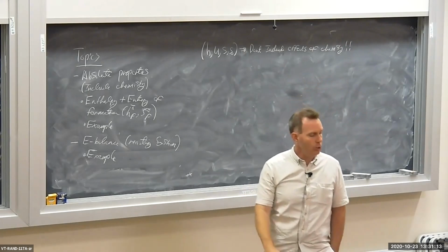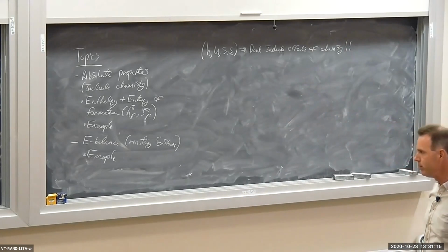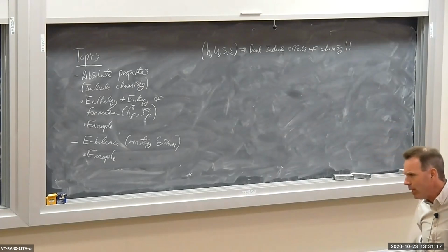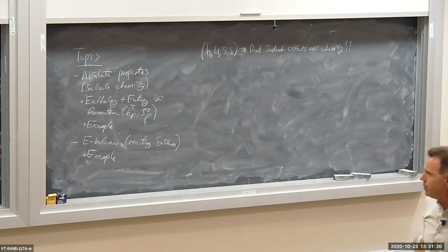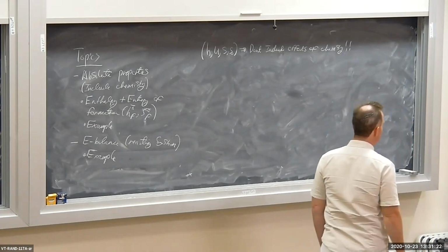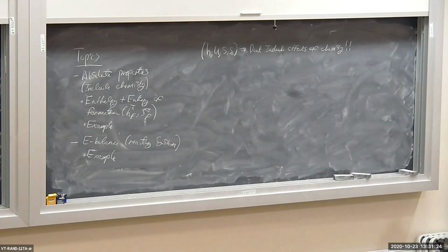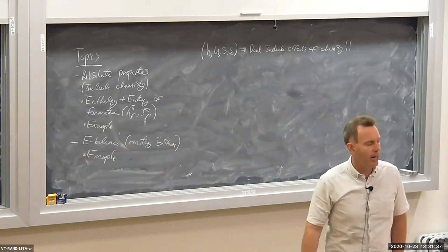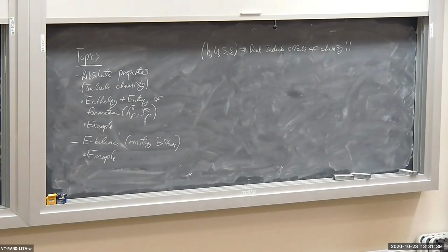That means we can't use the values in these property tables, the IGB air tables, the IGB tables, the steam tables, the saturation tables. We can't use these specific enthalpies and entropies directly in your energy and entropy balances. You won't get the right heat transfer. You won't get the right work because they don't include the effects of chemistry. So what are we going to do with that? What are we going to do to fix this? Well,